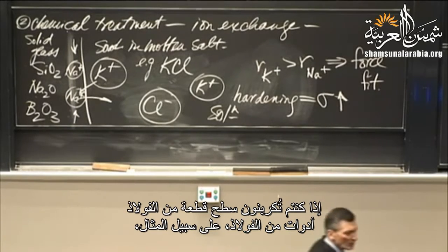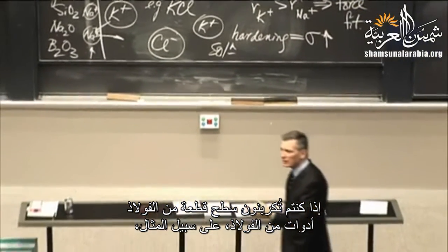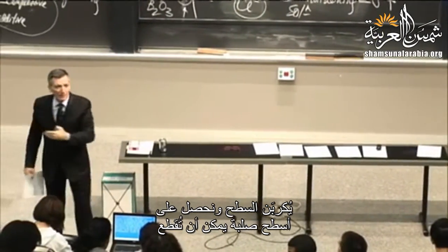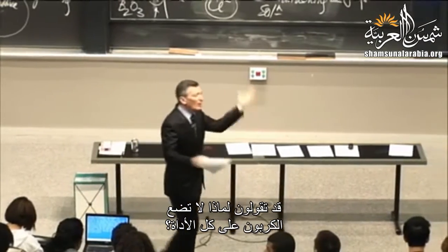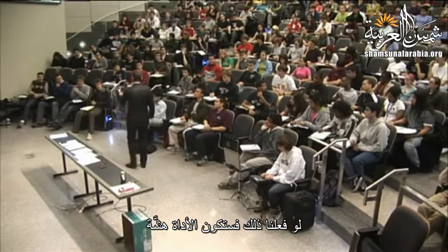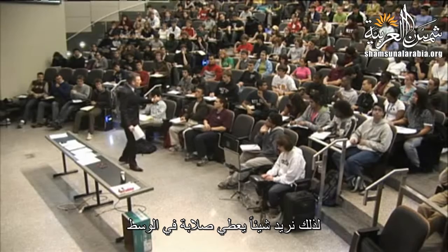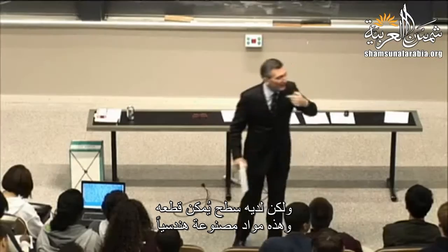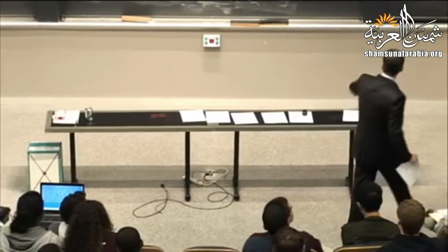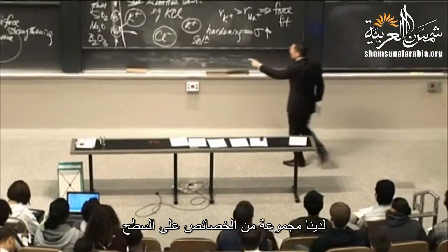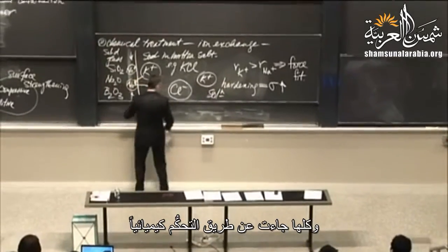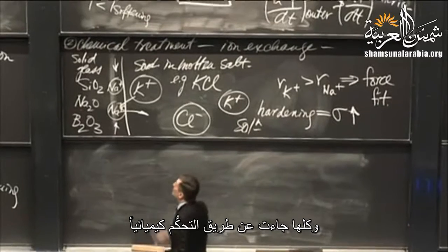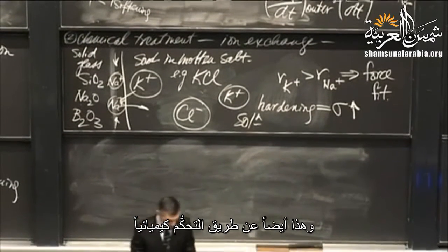If you carburize the surface of a piece of steel, tool steels for example, surface carburized, we get hard surfaces that can cut. You say, well, why don't you just put the carbon in all the way through? Well, then the tool bit will be brittle. So you want something that's got toughness in the center so it can take the impact, but it's got surface hardness so it'll cut. And that's an engineered material. We've got one set of properties at the surface, and we've got another set of properties in the bulk. It's all brought to you by control of chemistry.